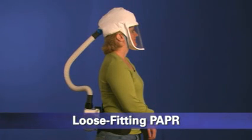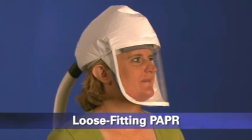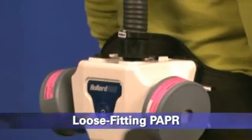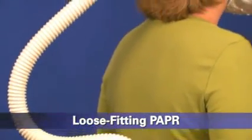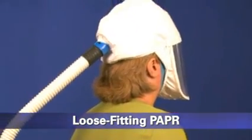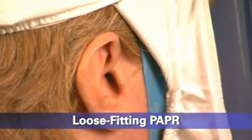This is a loose-fitting facepiece hooded powered air purifying respirator, also known as a PAPR. A PAPR has a blower that pulls air through attached filters. The blower then pushes the filtered air into the facepiece, which covers all of the wearer's face. Since it is loose-fitting, it does not need to be fit-tested and can be used by workers with facial hair.